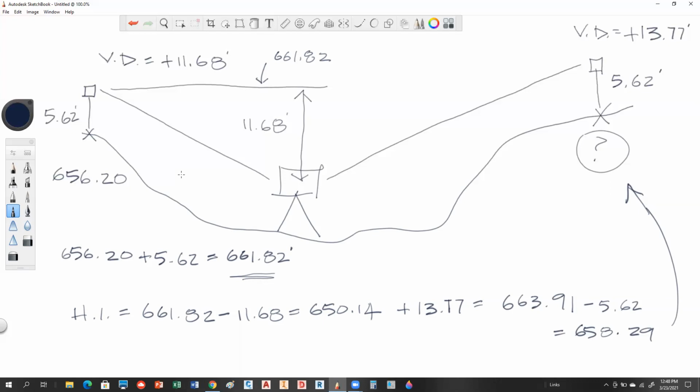And, you know, I think I've talked about this very often too, is that differential leveling is still better than this. There's too many errors that can be associated with trigonometric leveling. And all you have to do is just bump this rod and change it to a different height, and you screwed your system up, and that can make a huge difference. So got to be really careful.